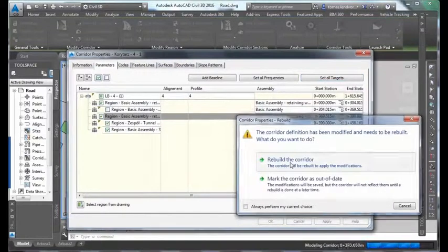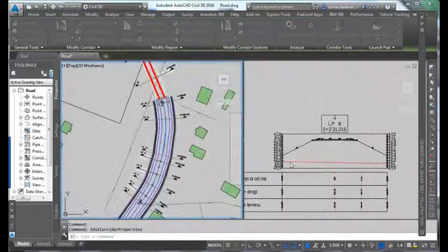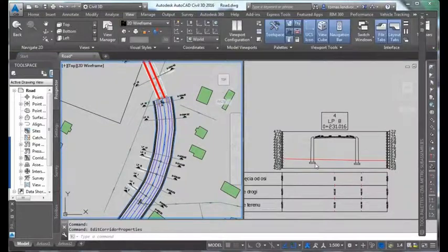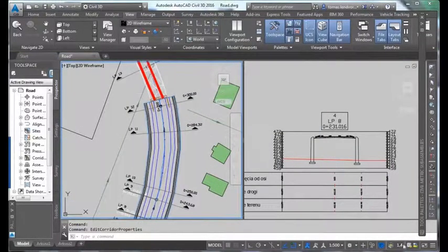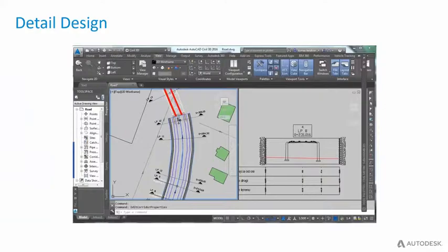So all this information can be defined. It's really up to me whether I have this information or not. And in a matter of a few seconds, I change my design. So from this fill which would destroy buildings, I put here a retaining wall, and I can continue my design. Obviously, now I can calculate the volumes based on cross-sections for different layers, etc.